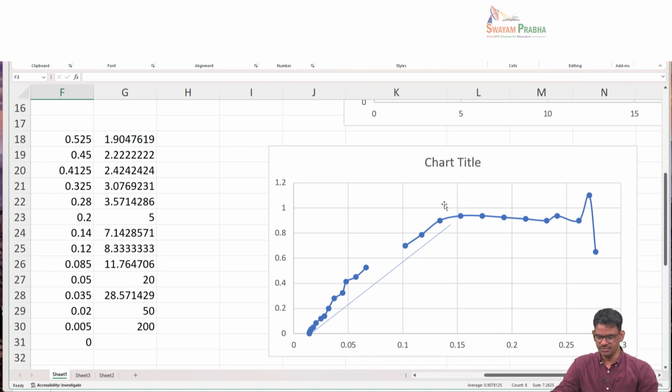And here we are making an assumption that this falling rate period is not sensitive to the change in air velocity. We are going to assume that changing the air velocity only changes the constant drying period, not the falling rate period. So between the test sample and the original sample, I am changing the air velocity. When I change this air velocity, I am only scaling the constant drying rate, and I am not changing the equilibrium moisture content, the slope, or the critical moisture content. Nothing is changed with regard to the falling rate. How do we justify this assumption?